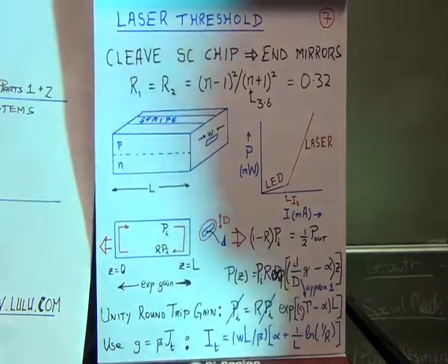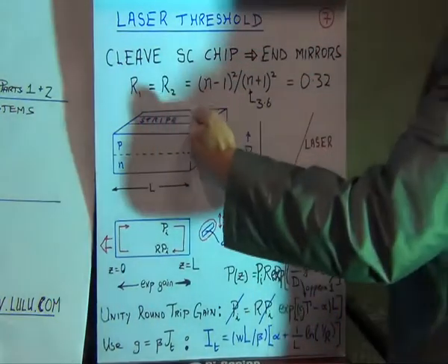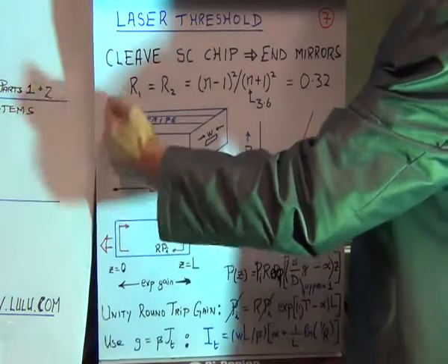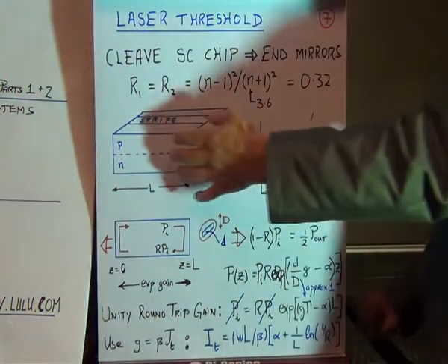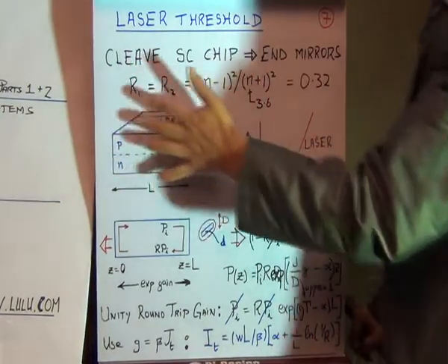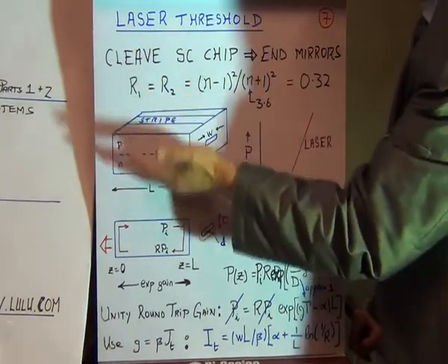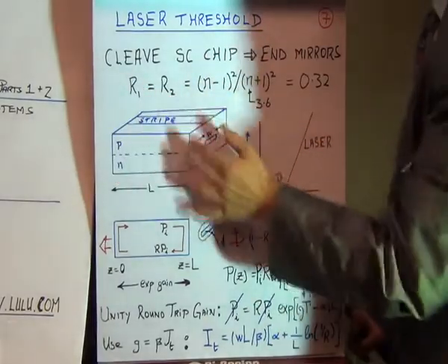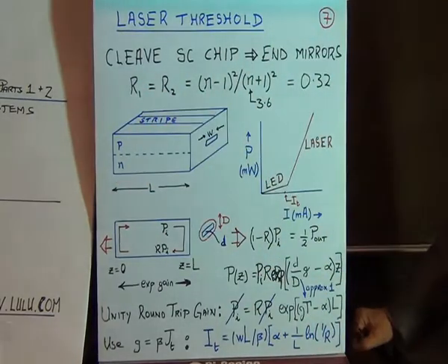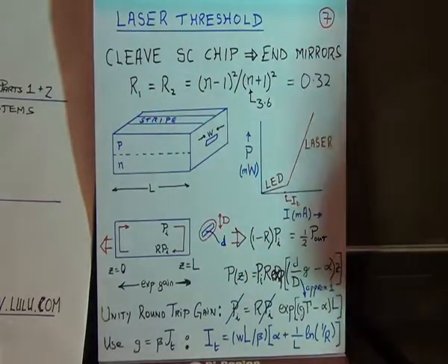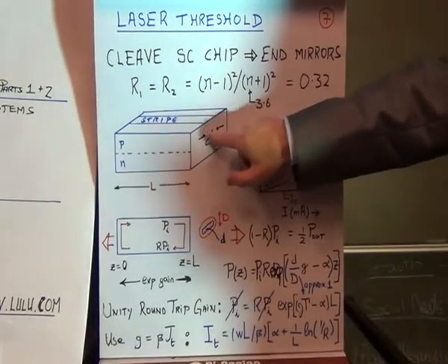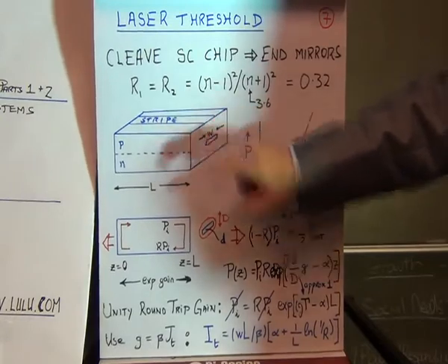LED into a laser? And we found we can cleave these end mirrors in the crystal. I've simplified the diagram now. This is probably a double heterostructure. All right, so there's many, many layers. But for the purposes of looking at how do we get to the pump threshold, we'll simplify it. There's the window that we had, the oval, a while ago.